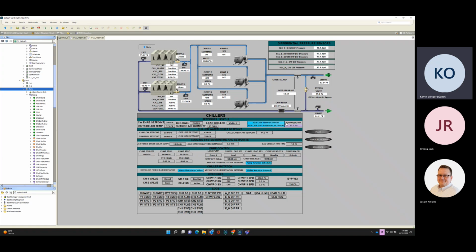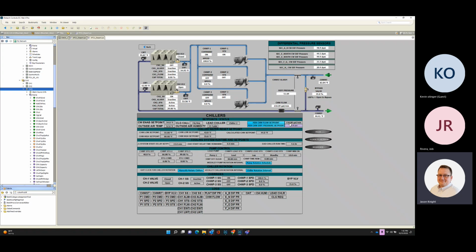And I'm assuming that is right above your cursor, right before the bypass? Yeah, right where I have the hand. I've got that hard coded at 150 gallons a minute. But where is it physically in the loop? Can you see me moving the thing here? Yep. It's actually in the pipe going from outside back into your chill water plant, your pumping plant. So it's in this return line from the machines right before the bypass valve. Okay, so it's before the bypass.